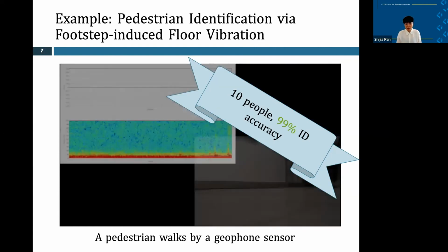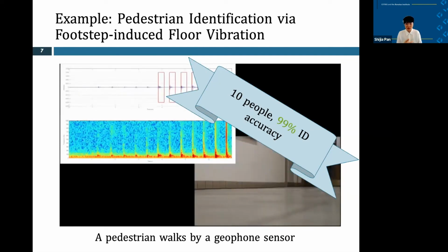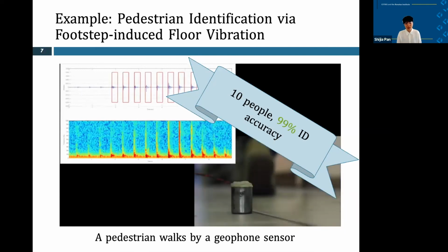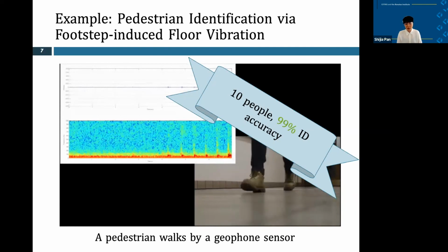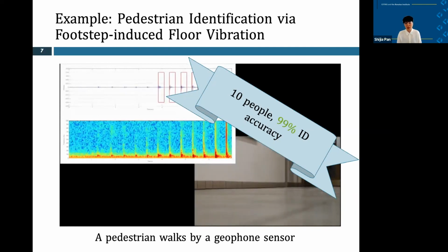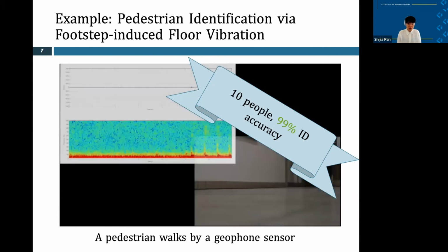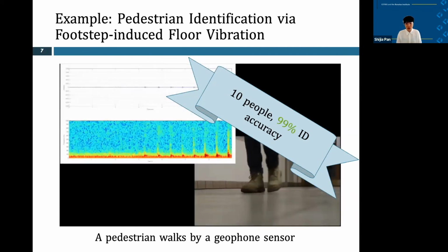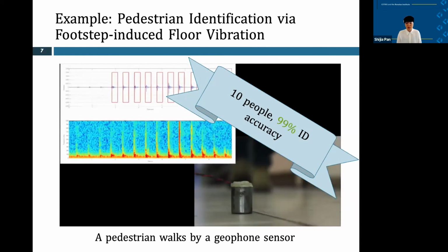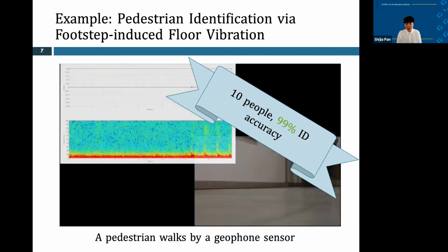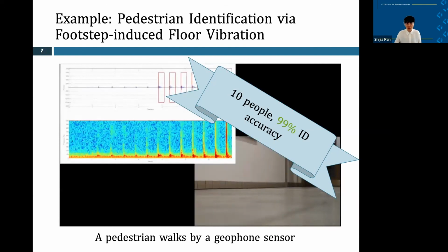When that happens, you might want to use a different hardware configuration so that it can acquire a better signal-to-noise ratio, or you want to place the sensor to avoid particular structural elements that will alter the propagation of the signal. Sometimes we call that a calibration for this particular system.